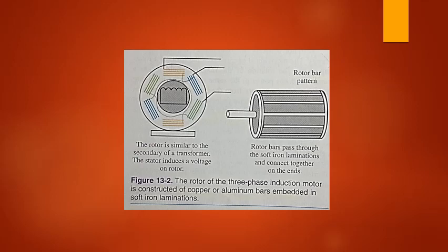The magnetic field on the rotor follows the rotating magnetic field in the stator. As the rotor turns, the rotor bars cut across the magnetic field produced by the stator. This action adds to the currents in the rotor bars. Note the similarities to the generator and transformer action. The term squirrel cage is used to describe the type of rotor in the common three-phase induction motor.